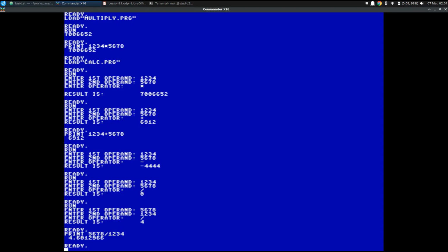But as far as this video goes, we're done. We could keep going with even more complicated math, but the building blocks you see here can get you most of the way as far as arithmetic goes. For more complicated things like trig functions, logarithms, and exponents, you may want to take advantage of the X16's banked RAM to make some big lookup tables for speed and accuracy. You can do any kind of math with the 6502, it just won't necessarily be fast or easy to implement.